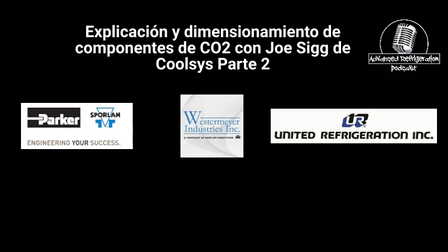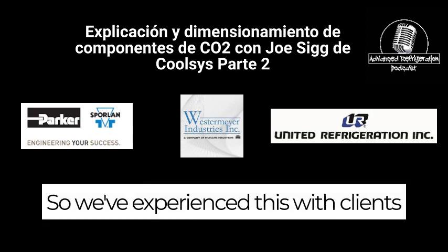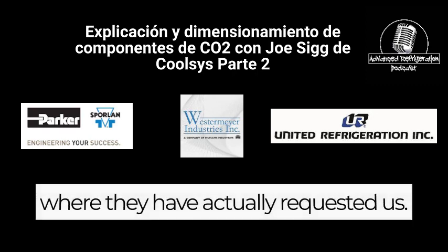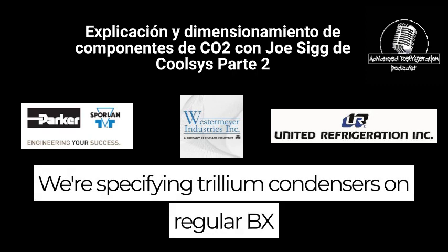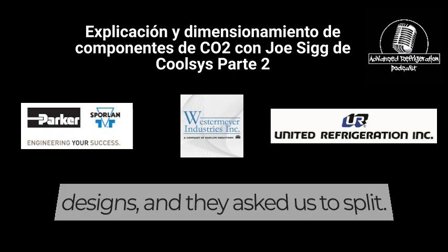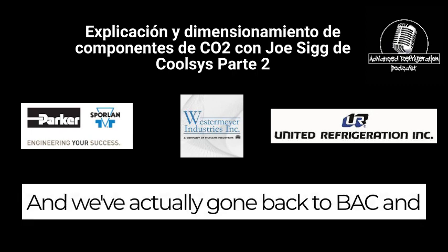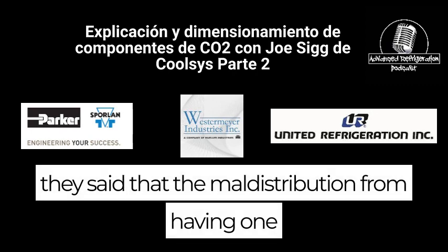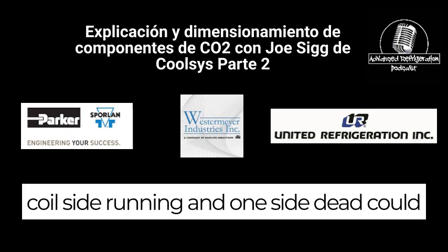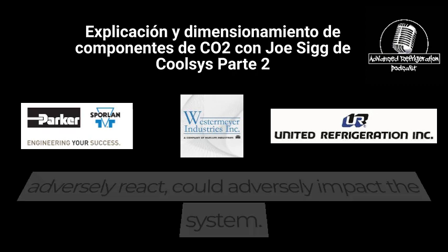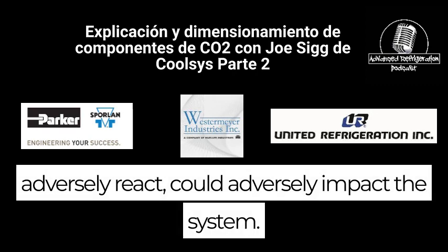Great question. We've experienced this with clients where they've actually requested it. We're specifying Trillium condensers on regular BX designs, and they asked us to split. And we've actually gone back to BAC, and they said that the maldistribution from having one coil side running and one side dead could adversely impact the system.